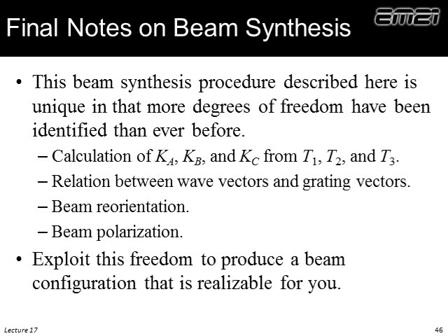So here are some final notes to come away with on holographic lithography. Unlike what you'll read elsewhere, this beam synthesis procedure is unique in that I've identified two areas where there's more freedom than we would realize. That was the relation between the wave vectors and the grating vectors, and also how we related the grating vectors to the reciprocal lattice vectors. That's where we use the matrix Q.